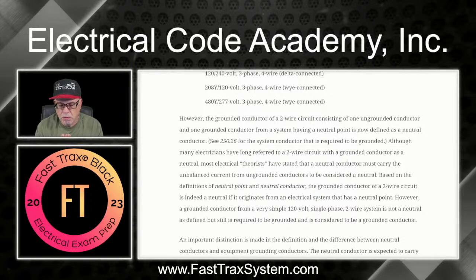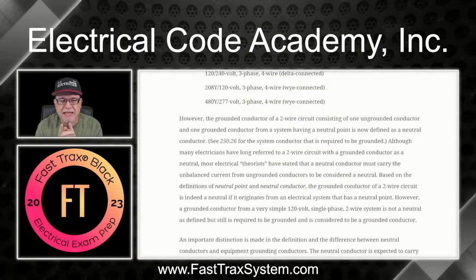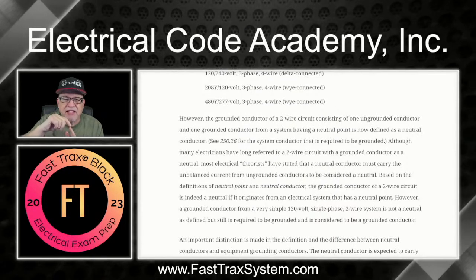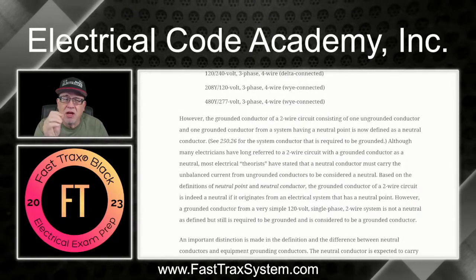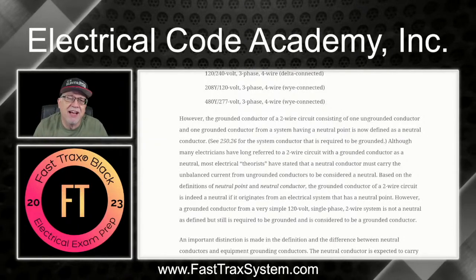Okay. Well, in a black and white circuit, ignoring the equipment ground right now, just the black and the white, whatever's going out, let's say you have 10 amps on the black, then you're going to get 10 amps on the white. It's alternating current, but again, it's going to have it. So is it carrying the maximum unbalanced load? No, it's carrying the load, no different than the hot conductor, right?